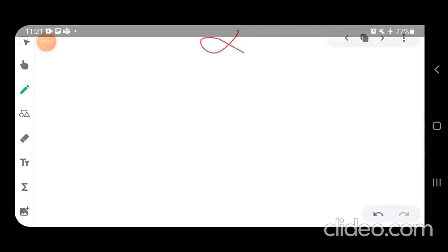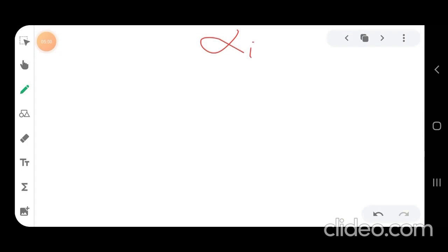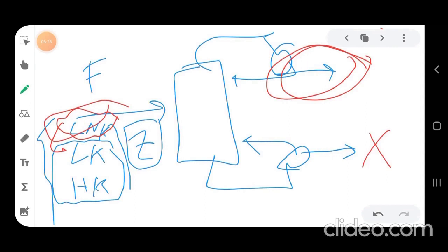values. Okay, and you know that alpha for any component i is the distribution coefficient of this component over the distribution coefficient of the heavy key. We refer everything with respect to the heavy key. So this will be the distribution coefficient of the heavy key. Okay, we refer everything to the heavy key. So start finding this relative volatility, and as we have three components here,